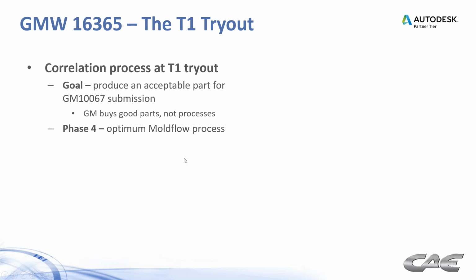So the first thing you're going to do at the T1 tryout is you're going to run the phase 4 Moldflow process. This is essentially what's going to be reported out in the final report for Moldflow. Those process settings are going to be input into the molding machine with the help of the tool shop that's running it.